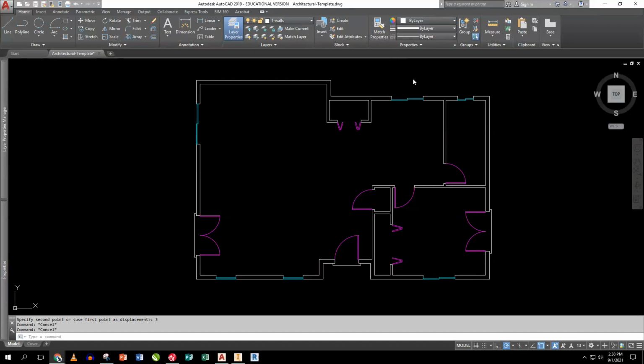So these you can see here are horizontal sliding windows, and these are single hung or double hung windows. Probably single hungs in this, because it's not fancy schmancy. I've also put in the stoops on the exterior doors because there's a stoop on this building, not actually a house. So they're in. I got the bifolds in on the closet here and here, the single hungs here, here, and here, and the double doors here and here, as well as the front door we already did.